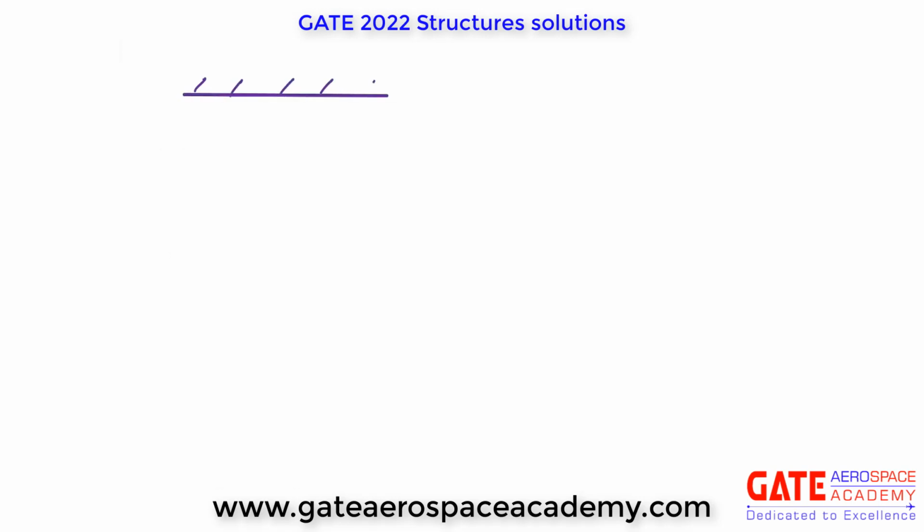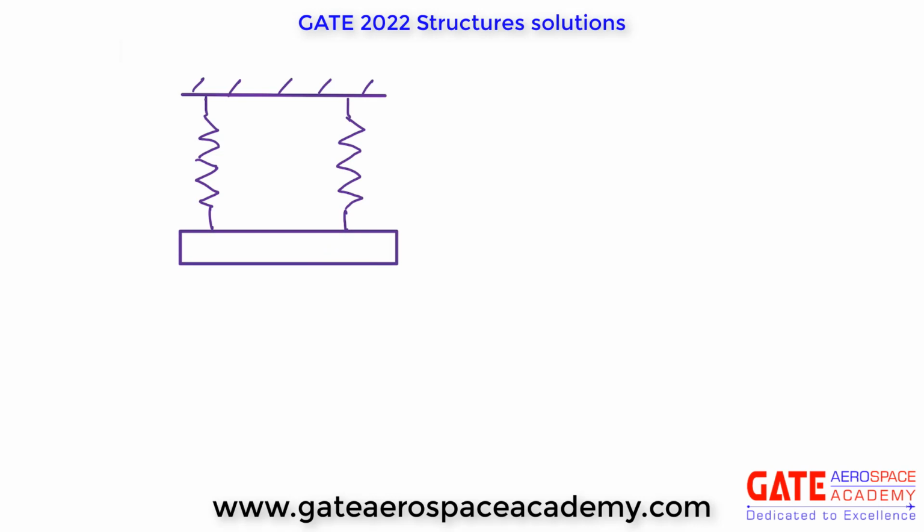So first of all, for mode 1, with mass m and springs k, k, let's write the equation of motion. m x double dot is equal to minus 2k x. So m x double dot plus 2k x is equal to 0.